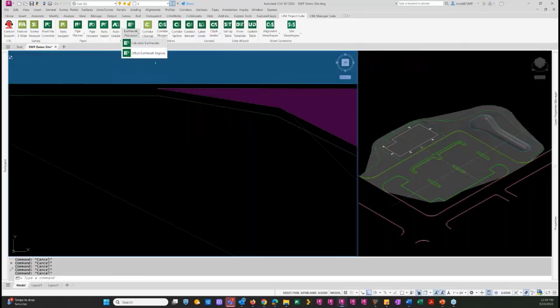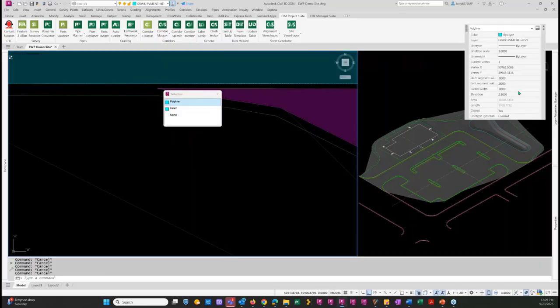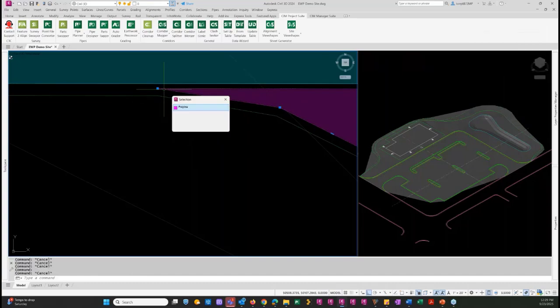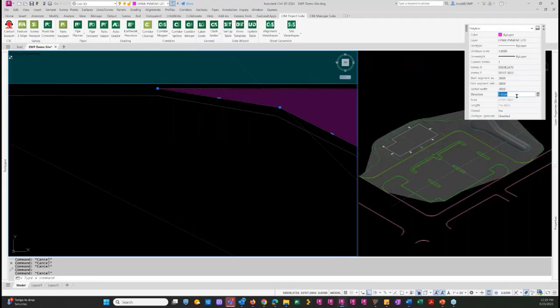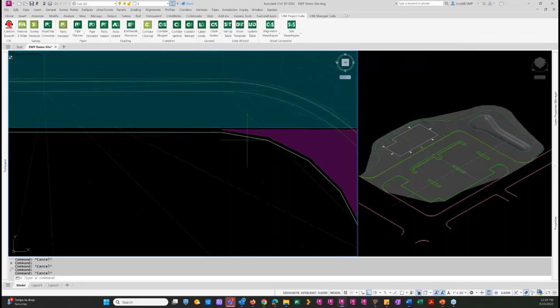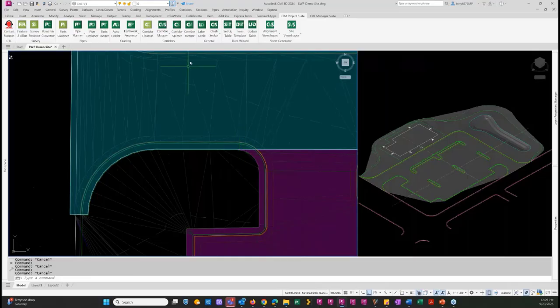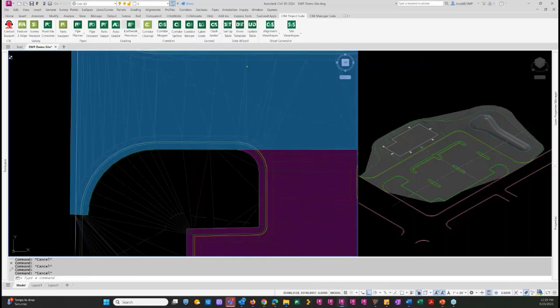Okay, so but if I change one of these, let's change them back to what they were, these polylines. When we open it back up, we'll see it's out of date, so we'll know that something has changed. So I'm going to change that one to 2. Let's change this one back to 1.5. Then we'll open the Earthwork Processor and we'll run it one more time.